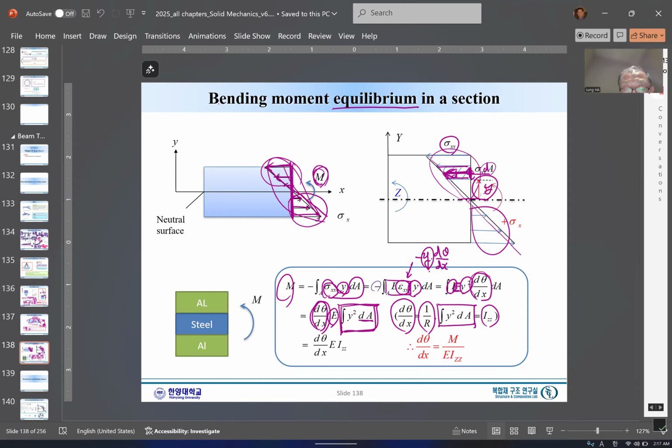instead of this, we write the bending moment of inertia and the y. And now this is the equation. So this was the unknown. And now, given in terms of the bending moment we apply, we can have it from the section modulus, which is given. So this was unknown, now it is given in terms of all known values.